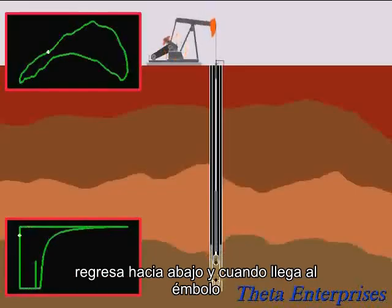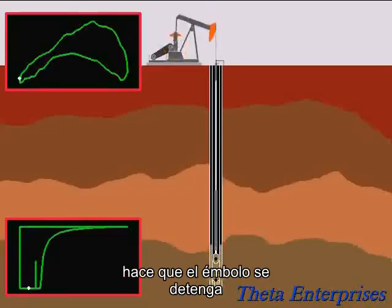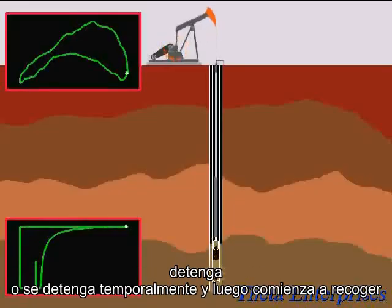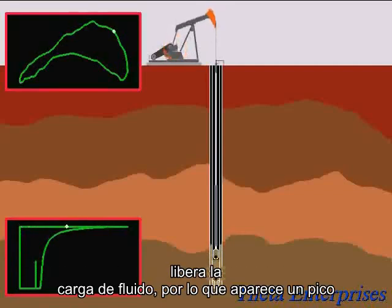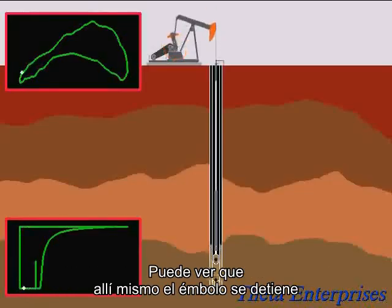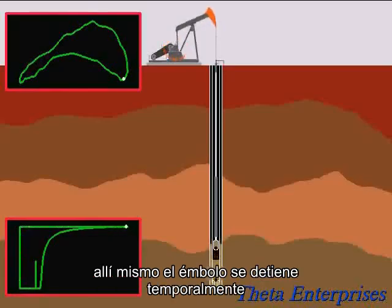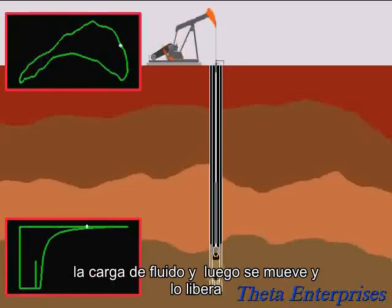When it reaches the plunger, it makes the plunger temporarily pause or stop, and then it starts to pick up the fluid load, and then it moves again and releases the fluid load. So you have a spike that shows up. That's the reflection of the sinker bars. You can see right there that the plunger kind of pauses temporarily, and as it does that, it starts to pick up the fluid load, and then it moves and releases it.